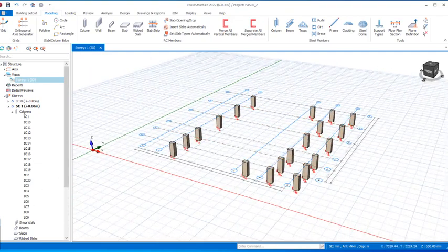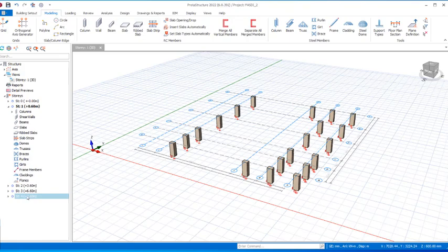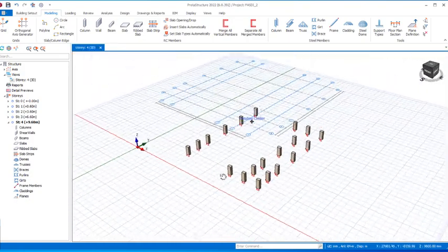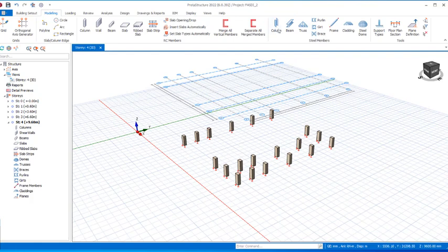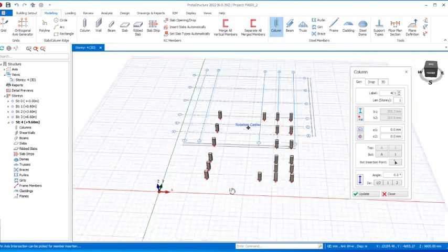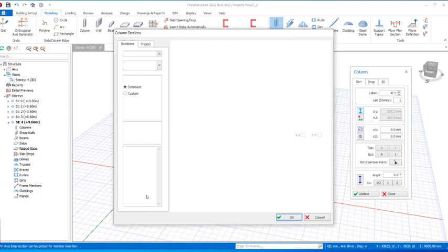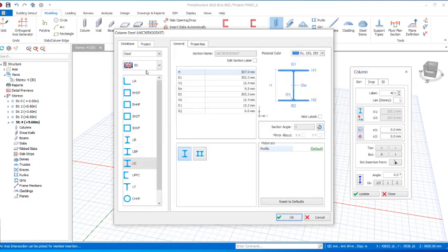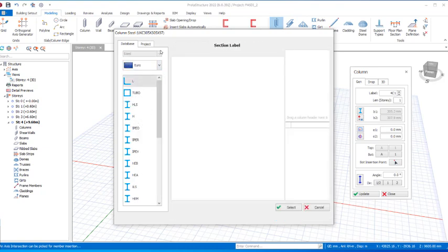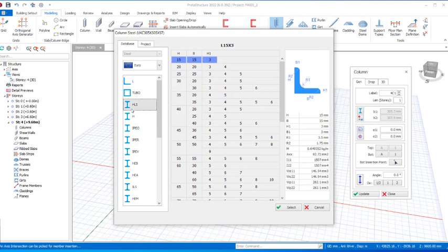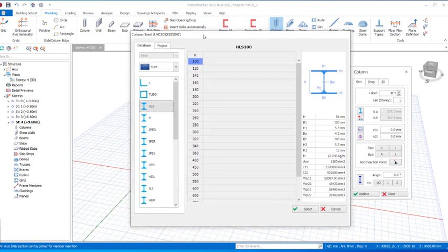After which we will navigate to story 4 right there. At story 4, we want to place the steel stanchions. For the steel stanchions, we navigate to the stanchions. You can see the steel columns right there. Click it once. Once it comes up just like this, we are going to be inserting the steel stanchions. We come to these provisions to select the sections we want to use for this design. You can see BS steel members. We click on the drop down menu and choose Euro Code members. We can also select other options.